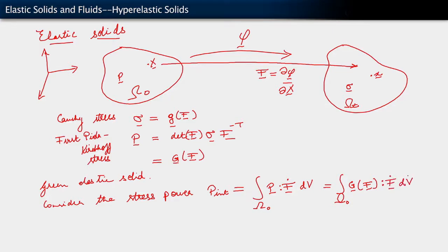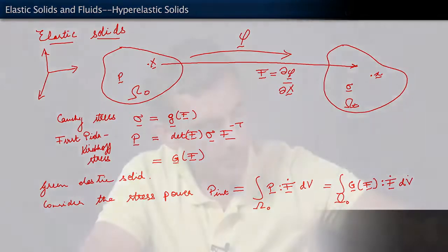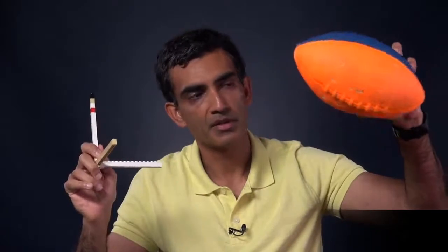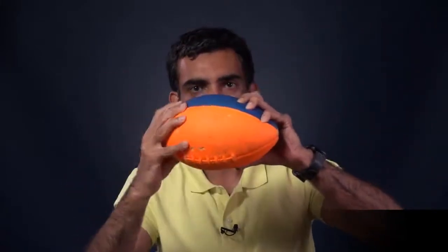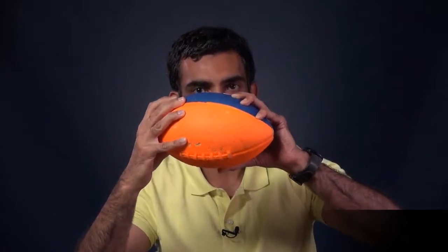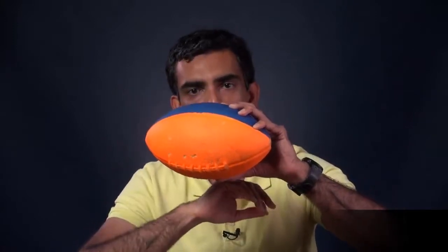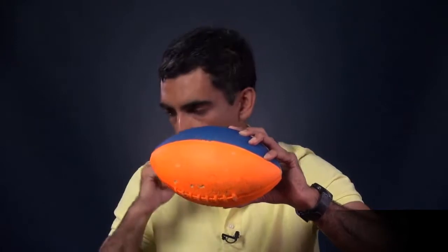Okay, so that's the internal power. What we want to think about now is that as we are deforming this body, this is the current configuration. Of course, we've written this integral over the reference configuration. So here's the current configuration. We're considering the stress power just mathematically by integrating over the reference configuration here. Okay, but we know everything we need in order to construct this integral.